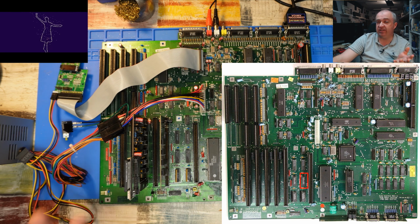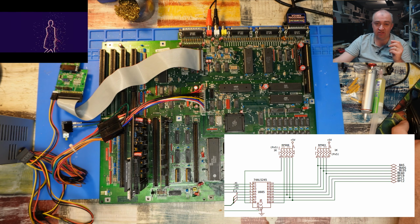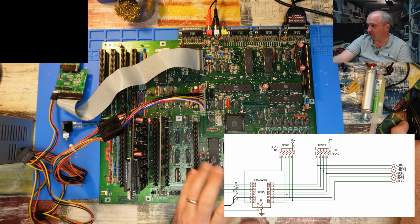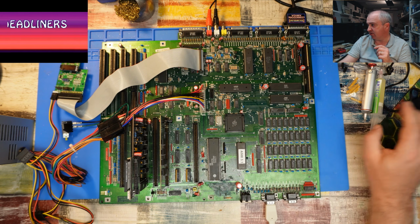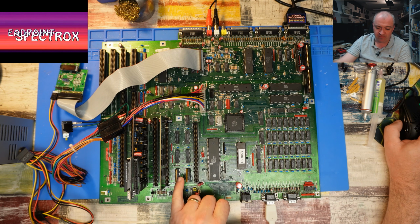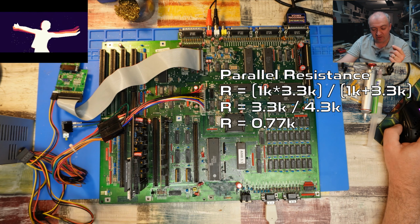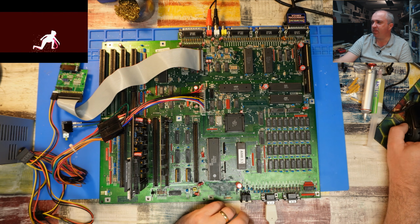And in fact, if we take another look at the A2000 schematics, there is no reference to that 3.3K additional pull-up. Now if you were to fit it along with the 1K pull-up when we're going to change those two resistor packs, that's only going to further strengthen that pull-up. If we run it through that calculator again, it brings it out to about 770 ohms, thereabouts. So ultimately, I don't really see the point.